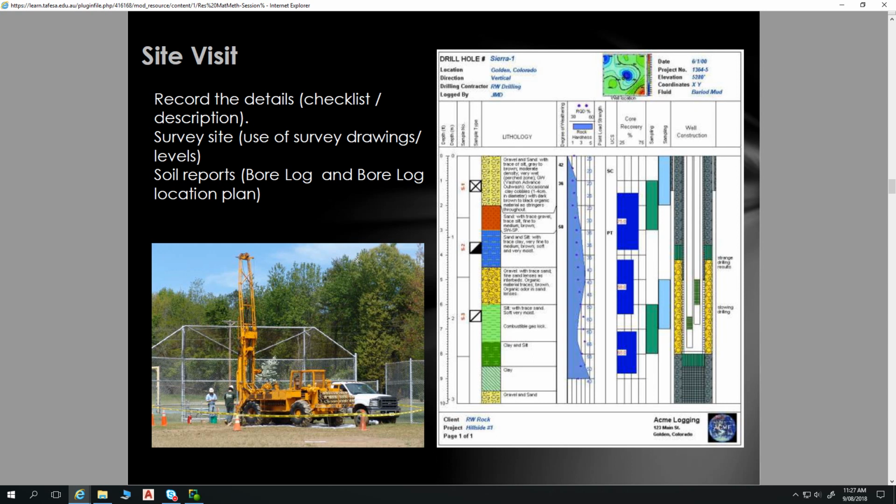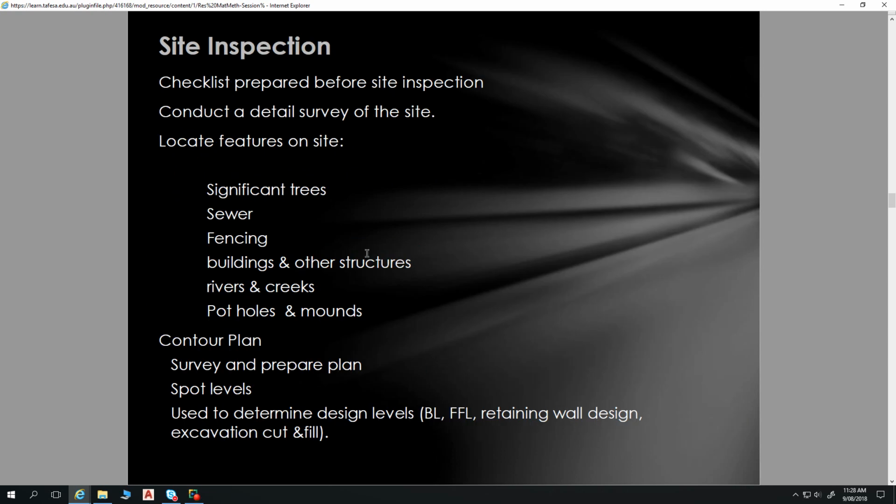But the thing that is of major concern to us here in Adelaide is how much that soil will react to moisture, how expansive that soil is. If it's this really solid green clay, then it's very, very reactive, and we get our reactivity expressed in Y values.